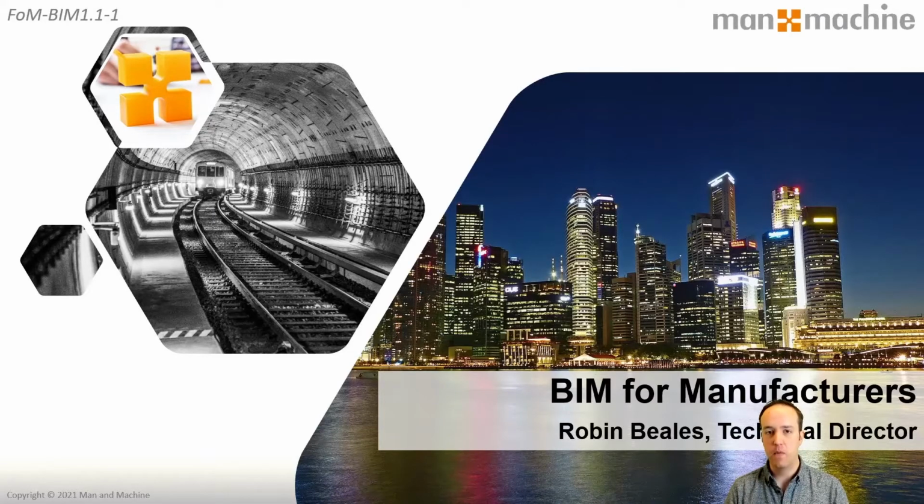So as I said earlier, within reason, we can do most things that either Inventor or Windows can do. So we could identify that the type of the component is a sheet metal component. And off the back of that, we could get it to A, generate a flat pattern if there isn't one already. B, update it if there is one. And then even go ahead and export the DXF files specifically for that flat pattern before linking them back to the files inside of the Vault. So great question, whoever that one was from. Thank you for that. And absolutely yes.